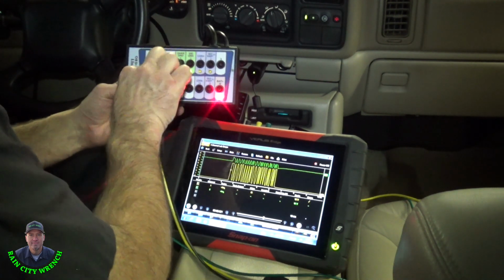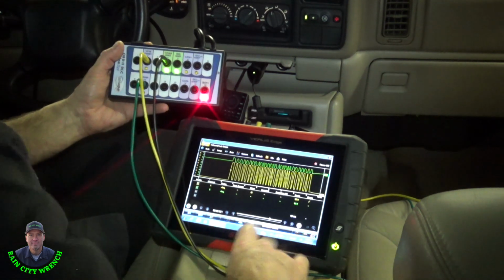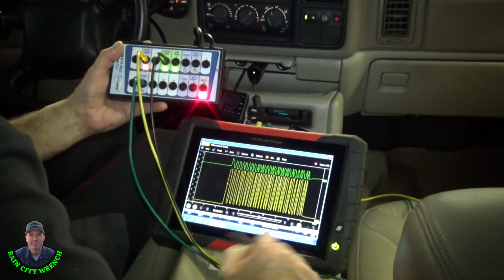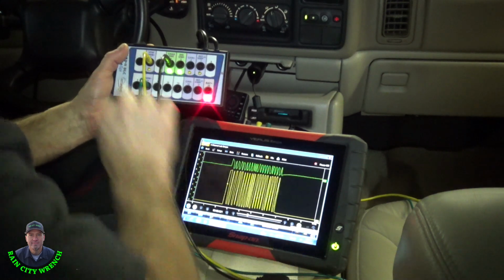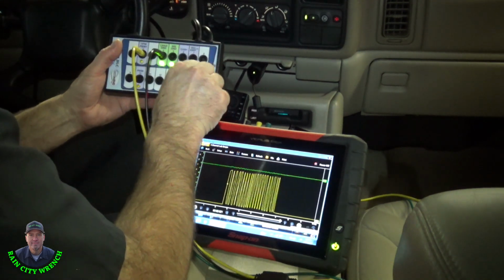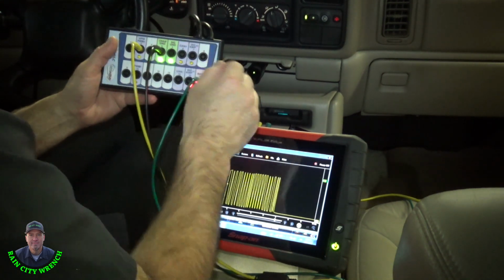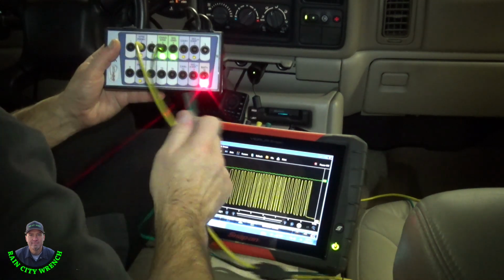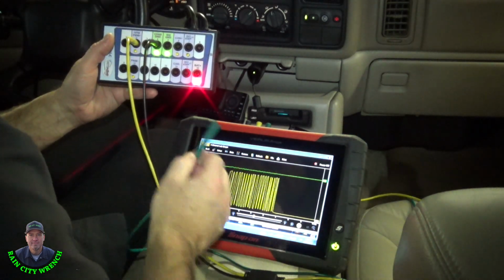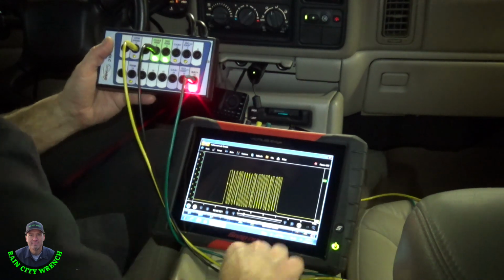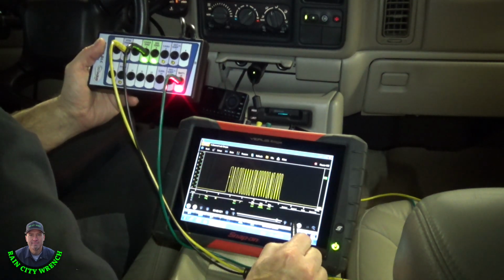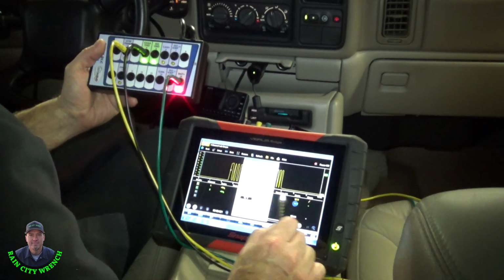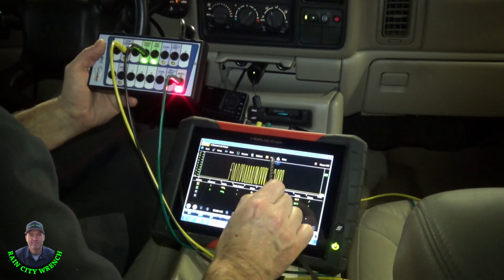Okay, now we can go over here and look at battery voltage on pin 16. One other cool thing is if you just got your standard banana jack leads, you just plug right in. So what we'll need to do is change channel 2 to 20 volt scale.